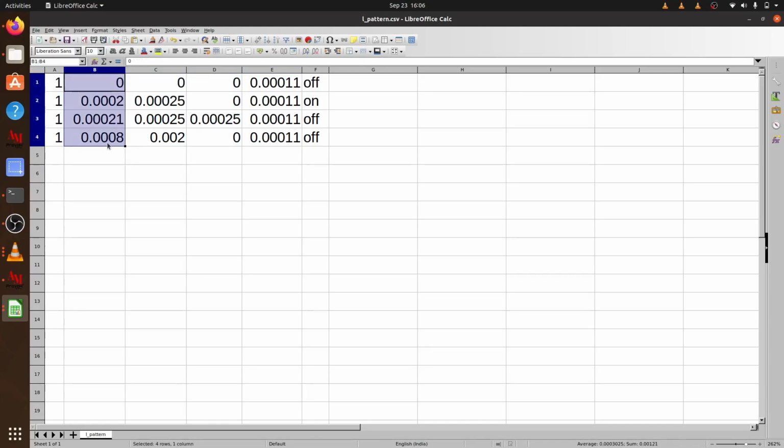To calculate the time, we will use the provided scan speed. Our scan speed is 1.25 meter per second. And we know the distance between each consecutive point. To calculate the time, we will divide this length by the scanning speed. So this will give us the time at B point. Similarly, to calculate the time at C point, we will add this time to the previous time. Since when moving from point B to point C, we have traveled the same distance, for the same scan speed, we will have an equal amount of time.